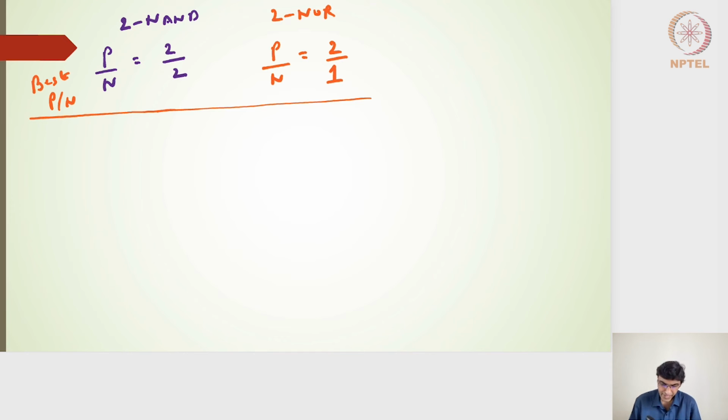Now, if I want to do an unskewed one, for the 2-input NAND gate, for an unskewed gate, it is actually a 4:1 ratio. Right? On the PMOS side, I need to have the size of 4 because, sorry, this is the 2-input NAND gate. So I will just erase it.